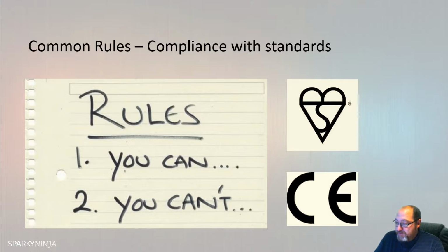Alternatively, if equipment complying with a foreign national standard based on an IEC standard is to be used, the designer or other person responsible for specifying the installation shall verify that any differences between that standard and the corresponding British or harmonised standard will not result in any lesser degree of safety than was afforded by compliance with the British standard. Such use shall be recorded on the appropriate electrical certification specified in Part 6.